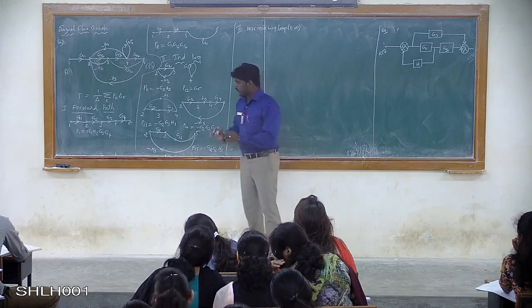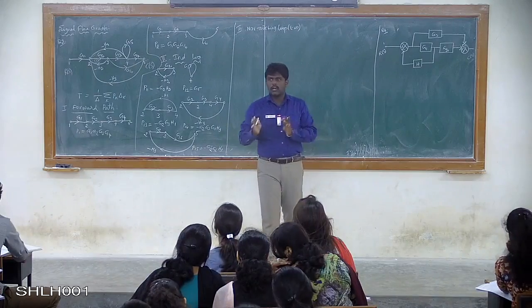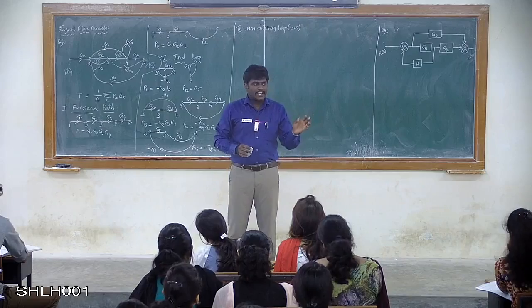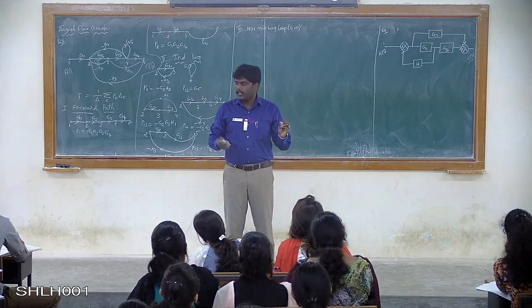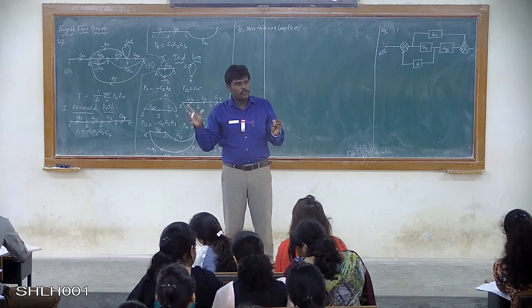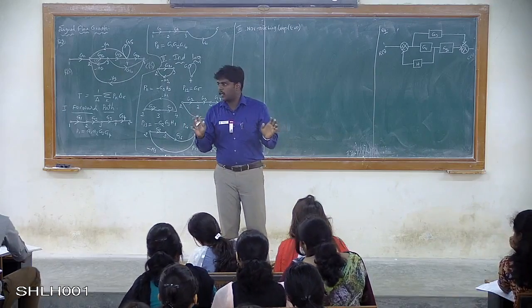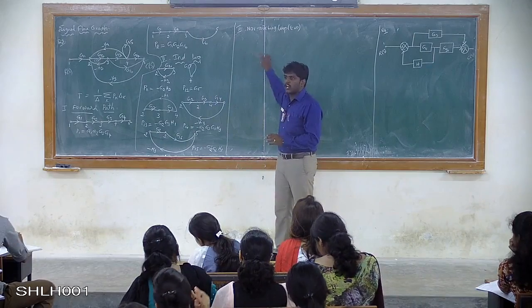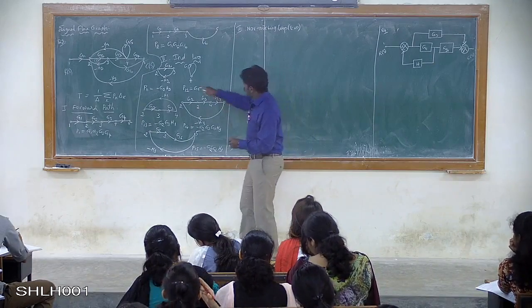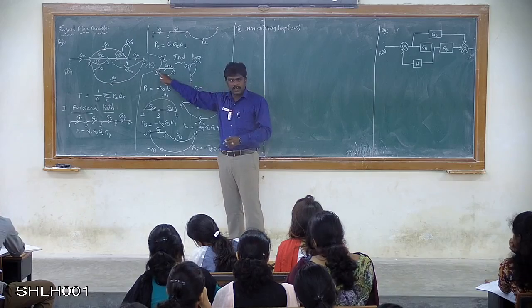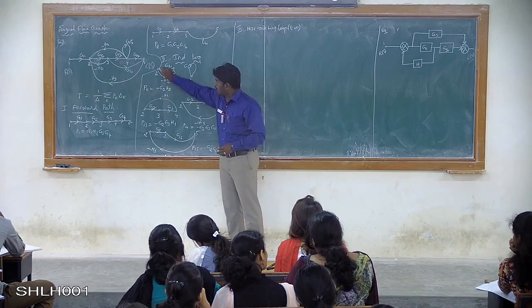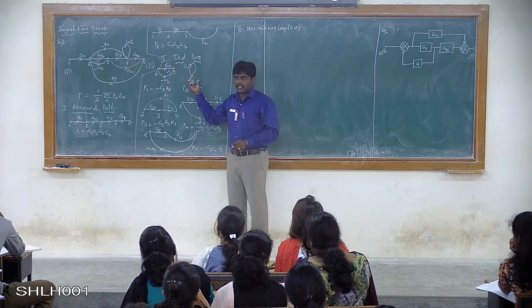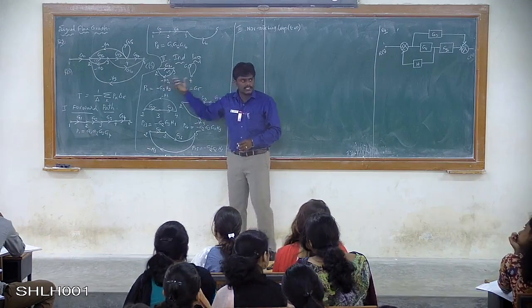So now, what are those two non-touching individual loops? One loop, let's say, is using the node numbers 2 and 3, and another loop is using the node number 4 and 5, meaning these two loops are not touching each other. So that can be taken as one pair of two non-touching loops, right? If I say this individual loop is using the node numbers 2 and 3, and this loop is using the node number 4, these two loops are not touching each other.